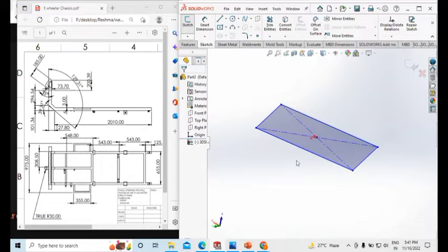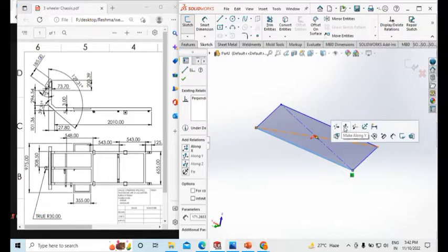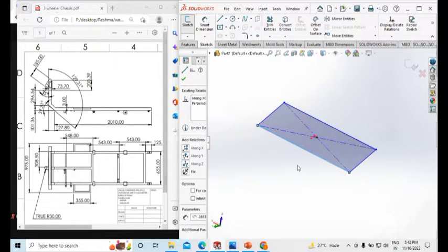Okay, so now this is our profile. Here we are giving constraints. Blue color means it is under constraint. We have to constrain it by restricting the degrees of freedom. Select on that, and here is an axis. We have to restrict the degrees of freedom along this axis. I'll give this along the x axis, which is required. This should be considerable.